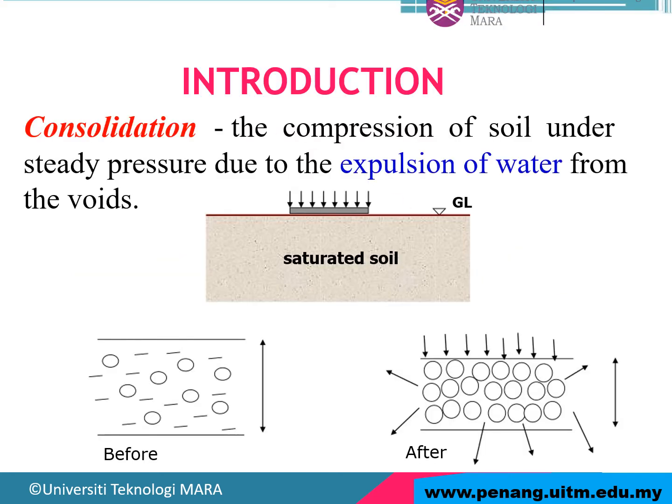So what is the consolidation? Consolidation is the compression of soil under steady pressure due to expulsion of water from the void. So consolidation is quite different if you compare to compaction. Compaction is expulsion of air. For consolidation, there is expulsion of water from the void.